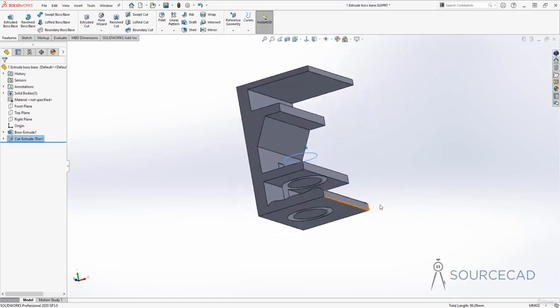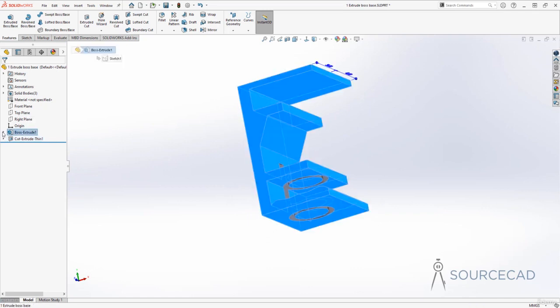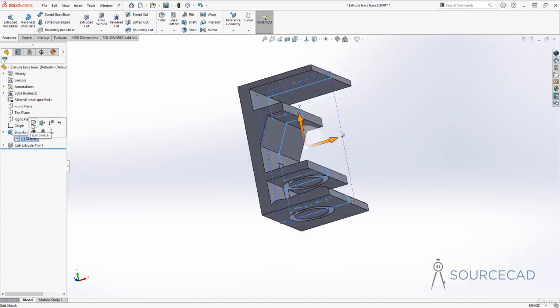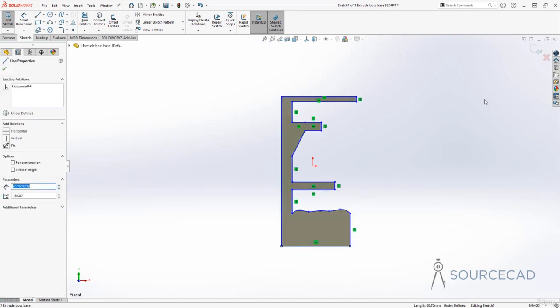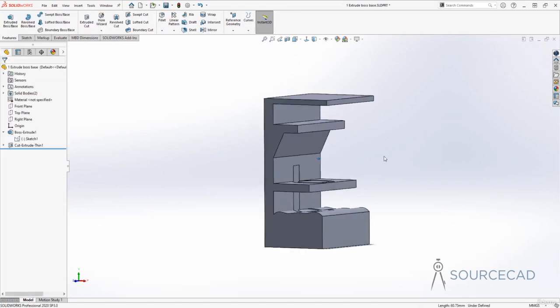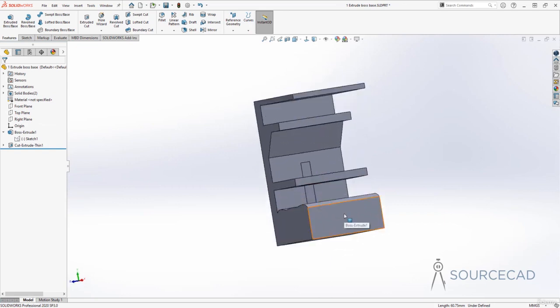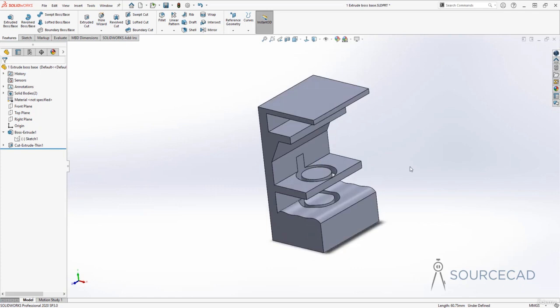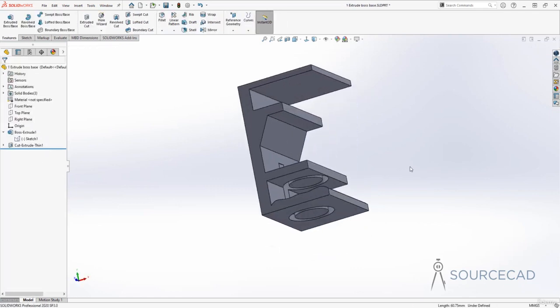But if you now change the sketch for this drawing, which I'll do using this boss extrude feature, I'll expand it, go to its sketch and edit, and if I increase the height here and exit this, then this is going to happen. There is no clean cut here because it will just cut only up to the point we specified. If, however, we change that, let me press Ctrl Z a couple of times so that we are back to this. And here I'll go to cut extrude and edit feature.